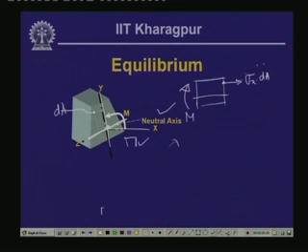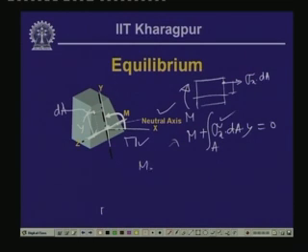The moment of this force is sigma x dA times the distance y. If we call this distance y, then moment m plus the integral of sigma x dA y over the area is equal to 0. Now, if we substitute for the value of sigma, this is m minus E by rho times the integral of y dA y, which equals 0.